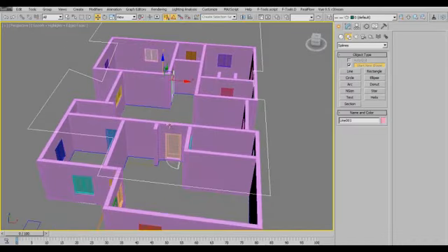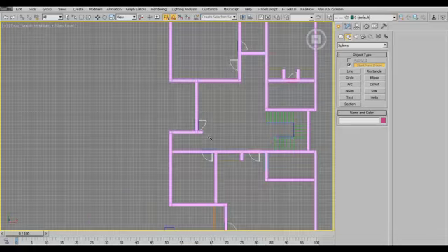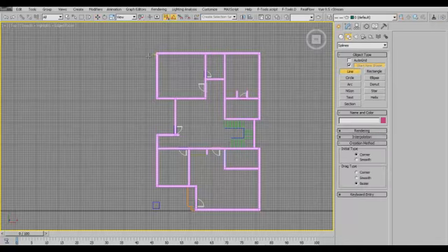So we're going to get rid of this. I'm going to delete this, then come back to my top view and create my wall using the 2.5 snap, which only snaps to the ground. It snaps to any point, but it places the object on the ground. So let's do that right now.